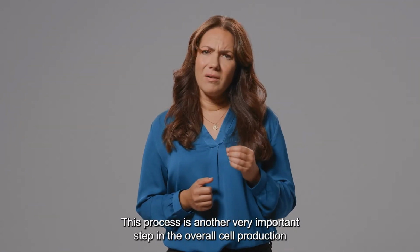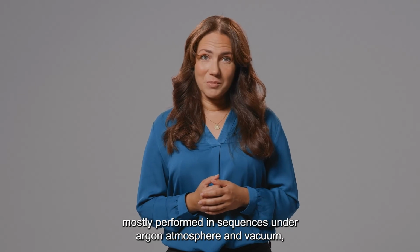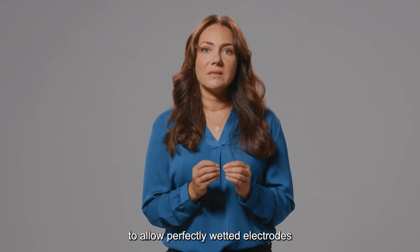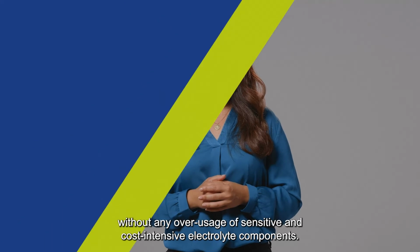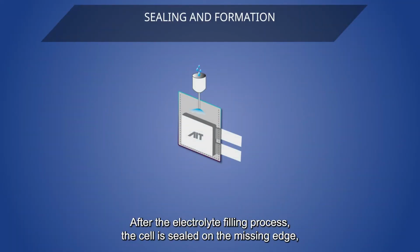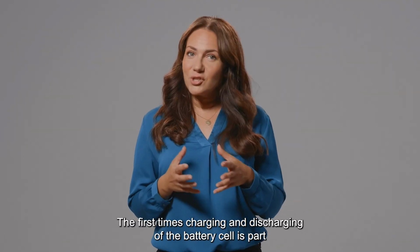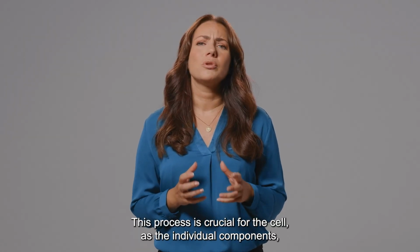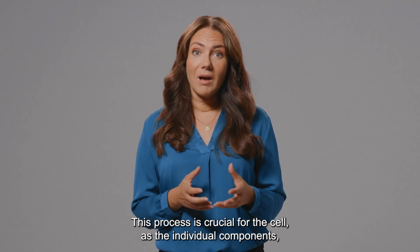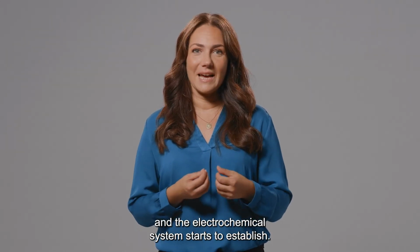This process is another very important step in the overall cell production, mostly performed in sequences under argon atmosphere and vacuum to allow perfectly wetted electrodes without any overusage of sensitive and cost-intensive electrolyte components. After the electrolyte filling process, the cell is sealed on the missing edge, leaving some space to allow gas formation during the initial cycling. The first charging and discharging of the battery cell is part of the formation process. This process is crucial for the cell as the individual components, after the electrolyte filling, meet for the first time and the electrochemical system starts to establish.